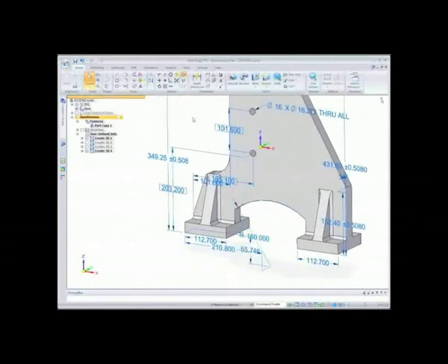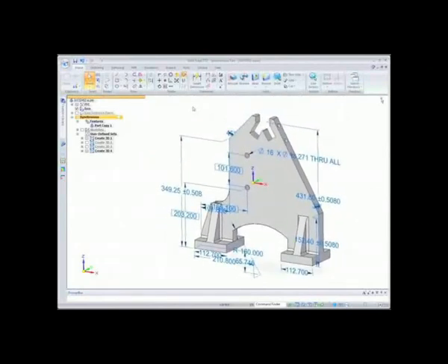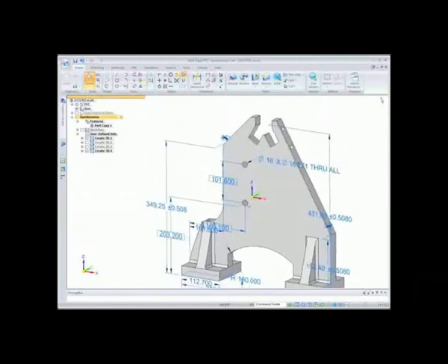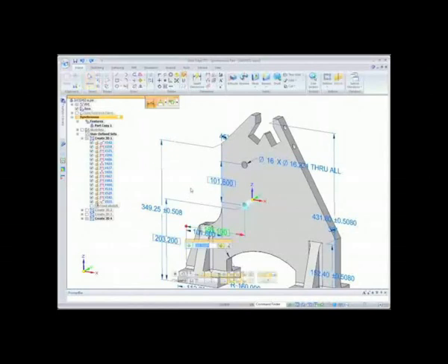Another important thing about Solid Edge when you're importing files is we can maintain design intent on the imported file. Traditionally, when you're importing geometry into a foreign CAD system, you'll lose the design intent. So for instance, what I'm talking about is we have a couple of holes there that are aligned along the z-axis. If I edit this dimension, which is only associated to the bottom hole, and begin to manipulate that dimension, you can see that it maintains that alignment along the z-axis.